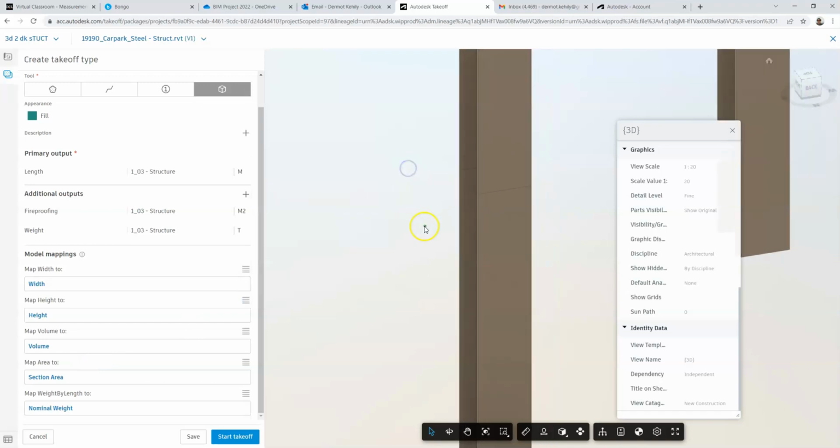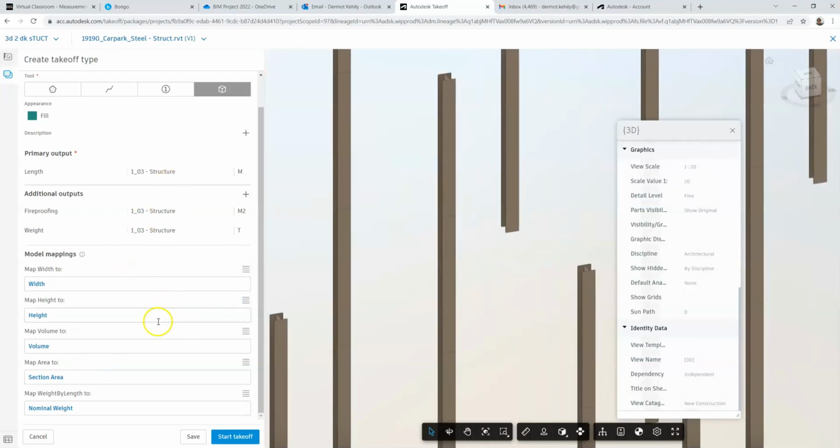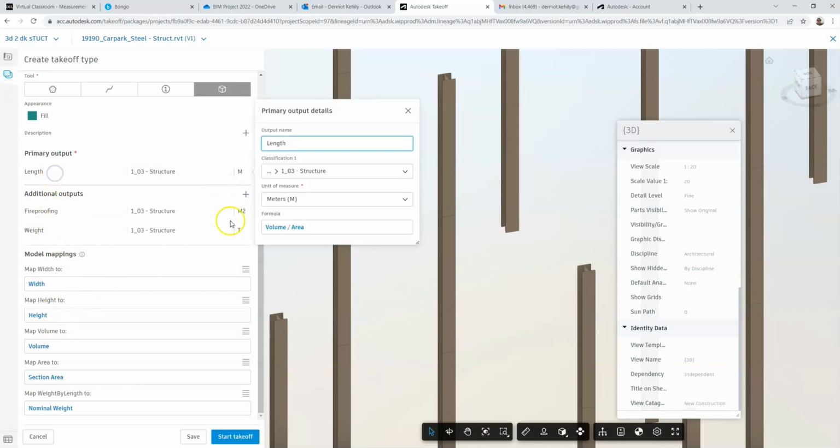So you can see that that's probably the trickiest one to do. You can copy that, I guess, when you're doing your beams as a duplicate, but make sure that you're mapping instead of volume divided by area in the beams here, it's going to be just cut length. So you'll type in length there, and then you'll map to your cut length. So give that a go.